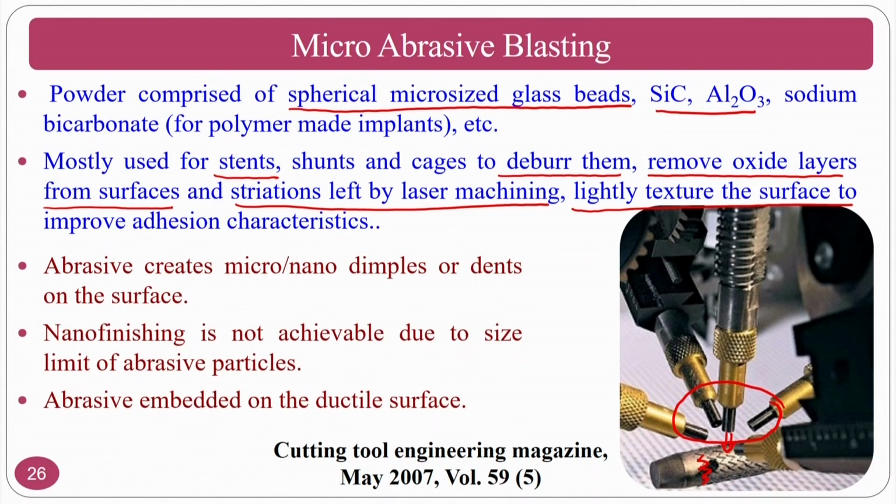So these abrasives create micro and nano dimples or dents on the surface. Normally for bio applications like stents, you require a super hydrophilic surface, because you have to have cell attachment, so that the artery attaches properly on the top surface of these coronary stents.